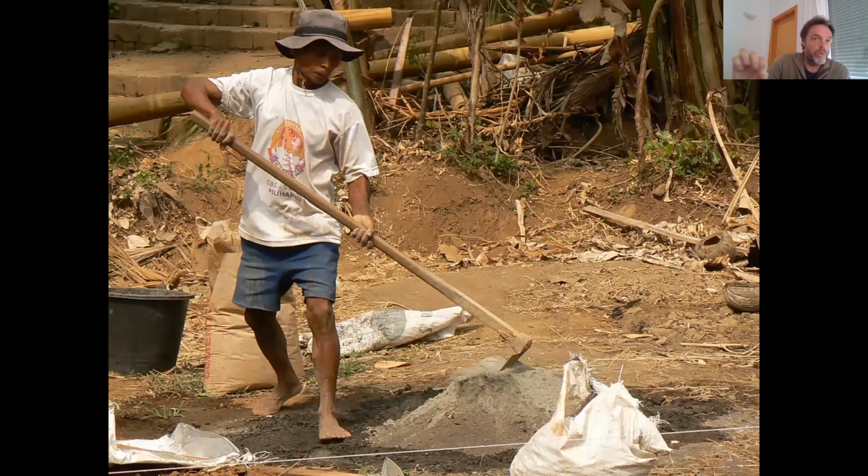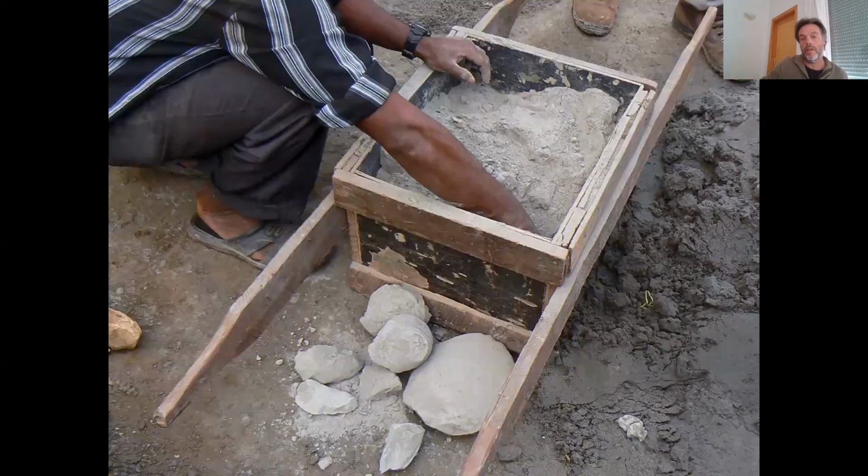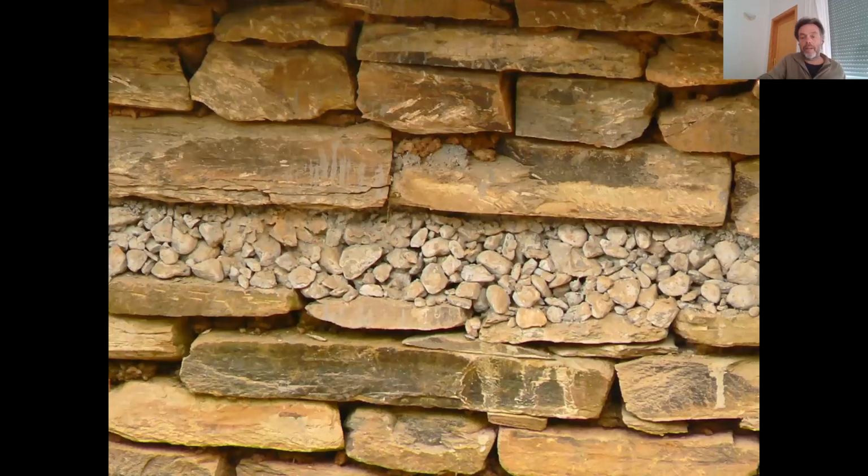For example, this is a picture I took in Indonesia. This guy is mixing mortar, but I also took a picture 30 seconds before this, where he lost half of his cement. This is very standard practice in all these countries. He was supposed to mix 1:4 or 5 or whatever, and it's now 1:10. This is a bag of cement in Nepal. It already started to harden due to moisture in the bag, but people invested $5 for this. So they're going to crush this old cement, which is doing nothing, and kick it back into the mix. This is the standard way of making concrete.